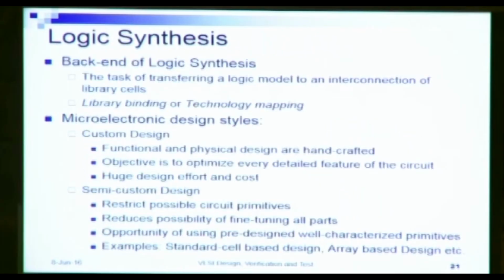Now we come to the back end of the logic synthesis step. The back end of the logic synthesis step does the task of transforming the logic model to an interconnection of library cells. This is popularly known as library binding or technology mapping. So it will take you from the gate level design to the transistor level design. Obviously, you can have many different designs in terms of the semiconductor technology here: TTL, CMOS, BiCMOS, etc.